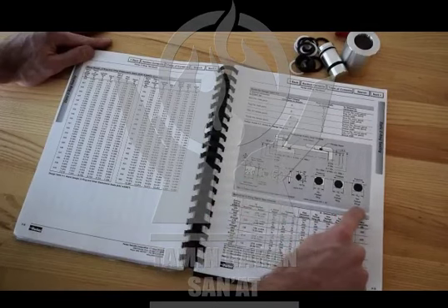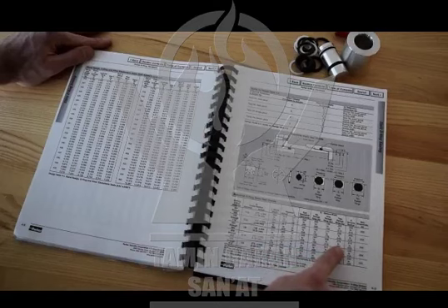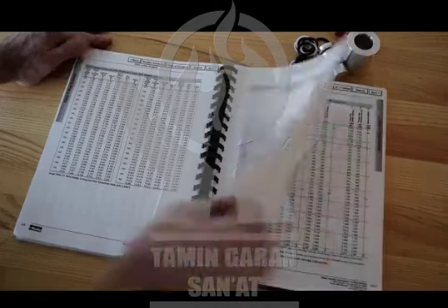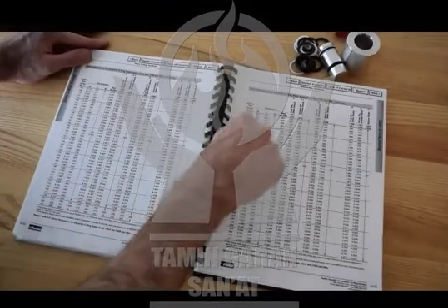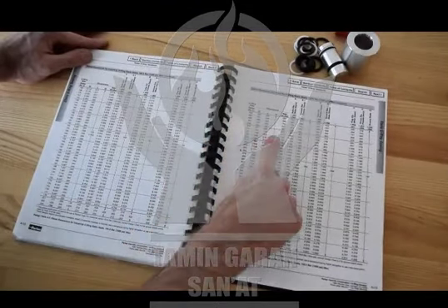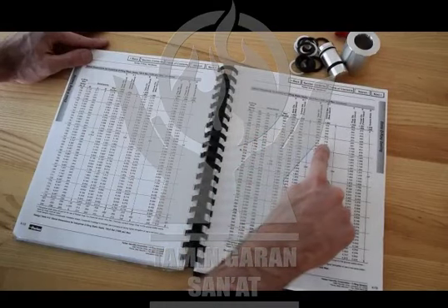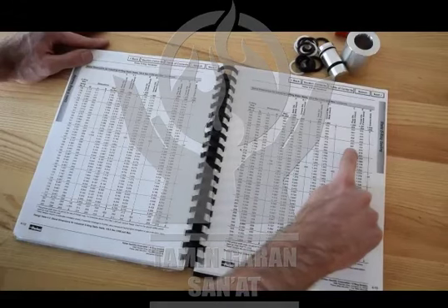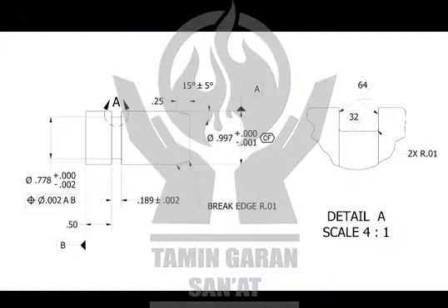We'll select the number of backup rings we're planning to use, then find the row for the 200 series O-rings in the table. Working across that row, we can read off the limits for the groove width. Then we'll turn to page 4-13, where the 200 series O-rings start. We'll find the 210 O-ring, then work across the row to read off diameters A, B1, and C. You'll notice that the tolerances for these dimensions are given at the top of the table. Then, all we have to do is transpose this information onto our drawing.